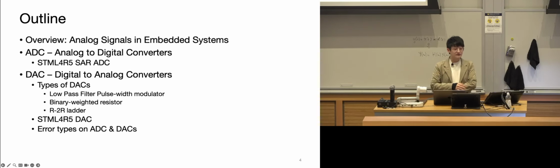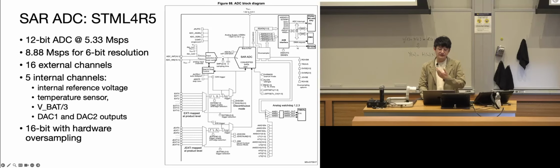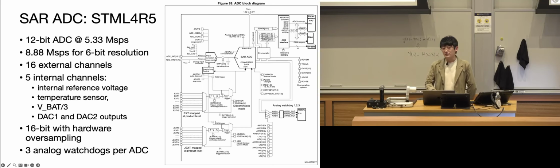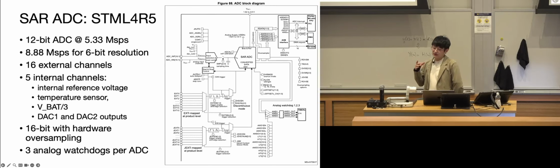So we already talked about this. These are the ADCs we have on the board, with various external channels and also internal channels, and you can set those ADC channels to different resolutions, topping out at 12-bit. We also have the analog watchdog per ADC, which is mainly used as a hardware threshold monitor. We'll talk about this in more detail later in the slides.